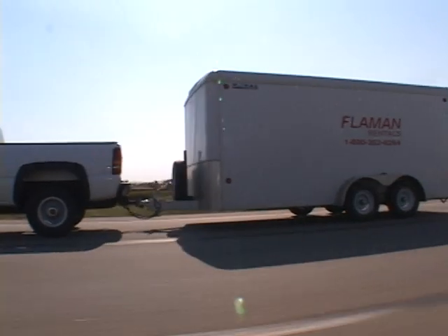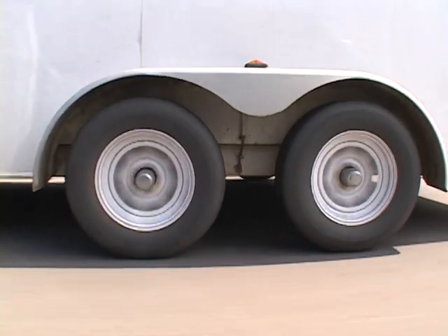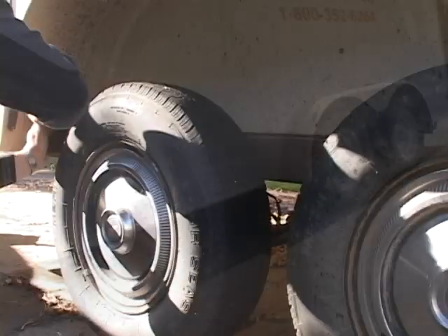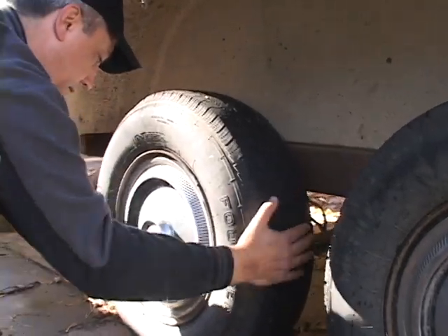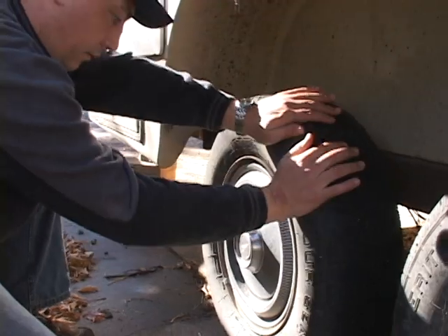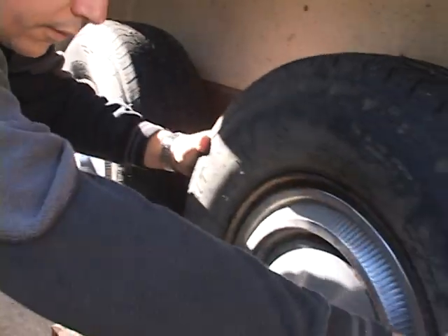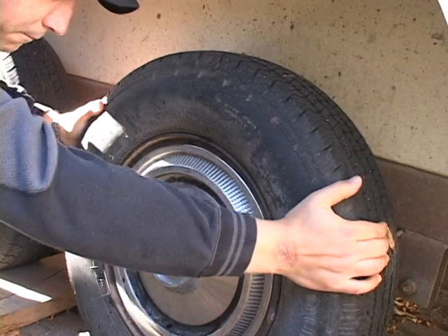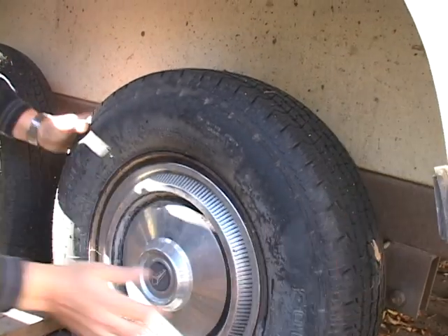Always check for tire wear. Tire and wheel safety should also include review of wheel bearings. This can easily be checked by firmly gripping the tire and pulling on the wheel. Any play or lateral movement of the wheel housing can indicate bearing wear and a need for maintenance.